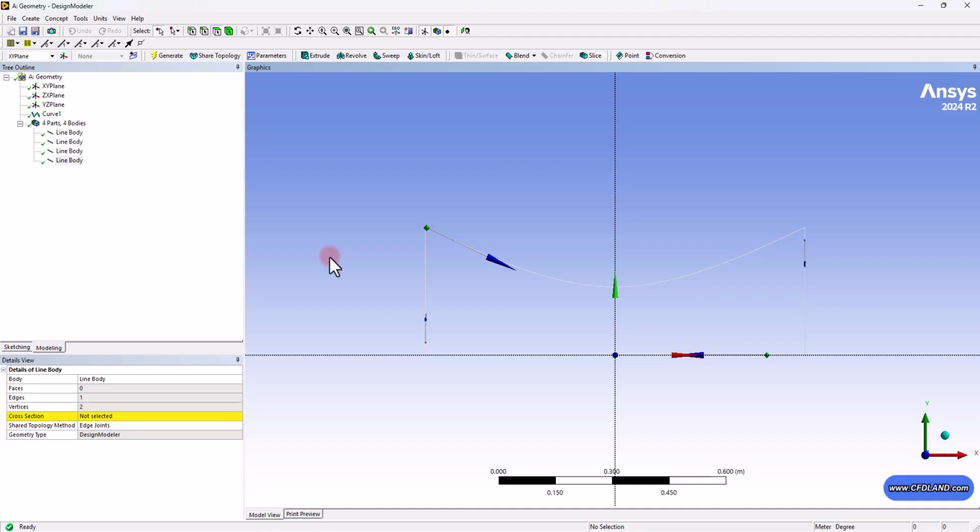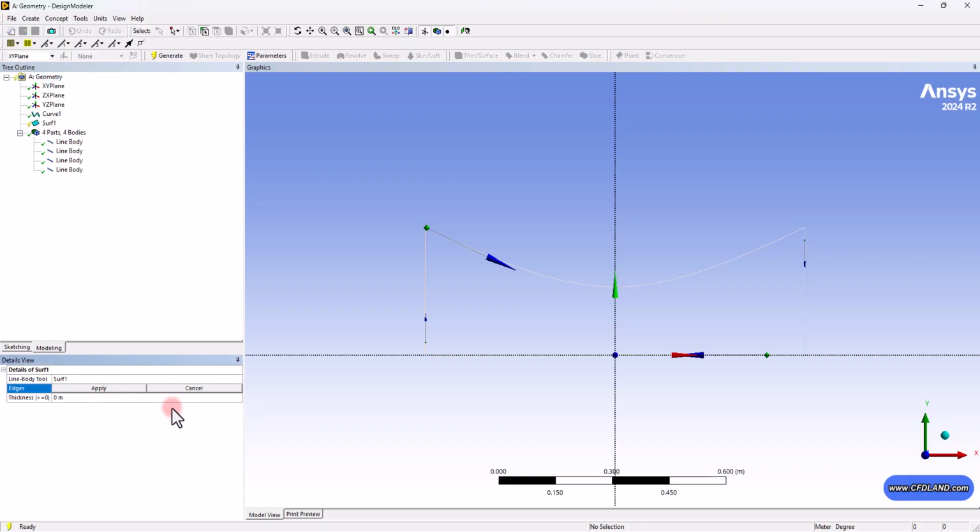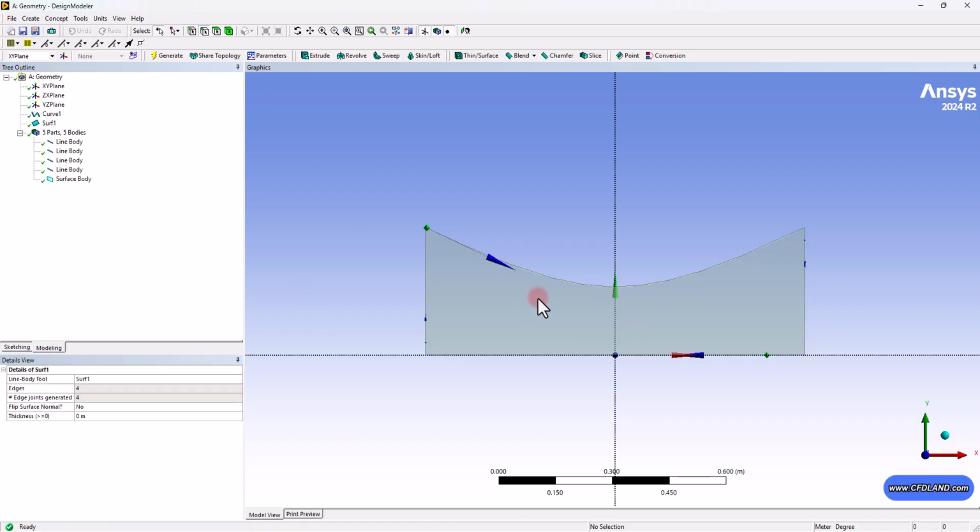We have to convert it into a surface area because this is a CFD simulation and we are not working with edges. In order to do so, once again, following the Concept tab, you can see the Surfaces From Edges tool. What you need to provide for the software is just a closed curve for the software to group them together and find the space between them as the surface or our computational domain. Holding down the Control key, I select these four edges together and apply them. Without any thickness, we can generate that. And this represents the whole nozzle geometry.